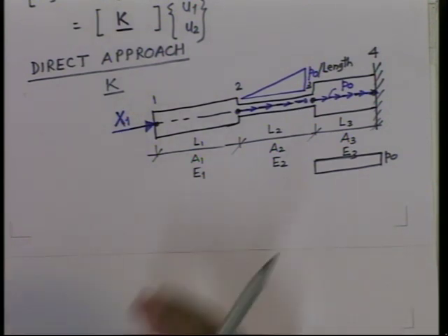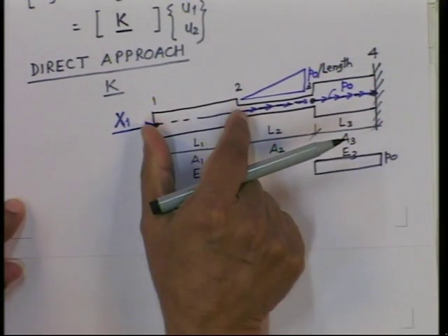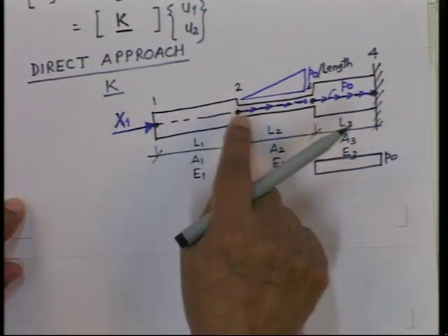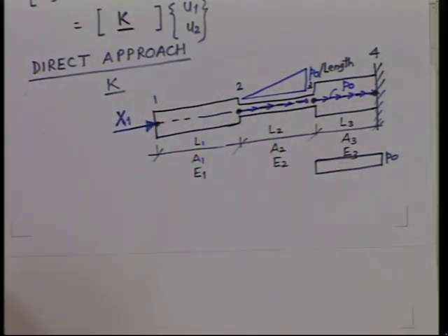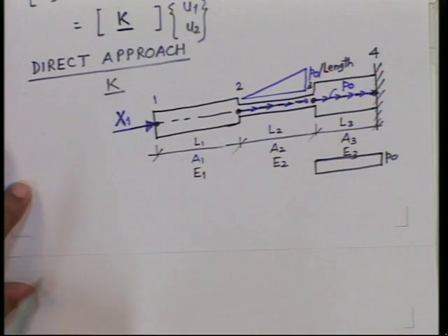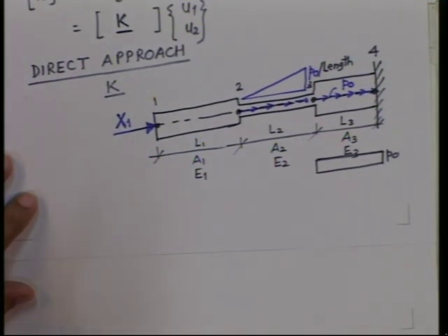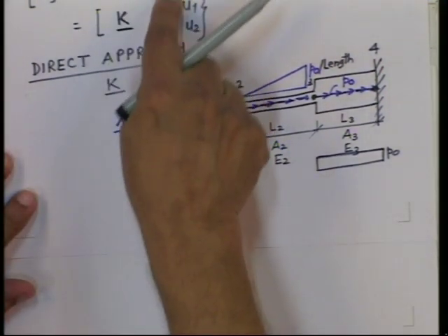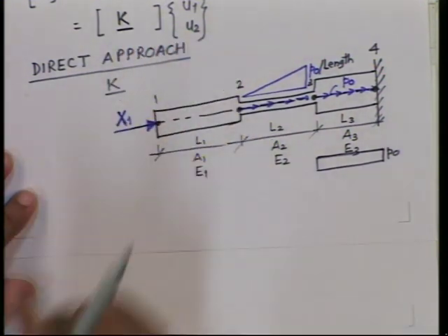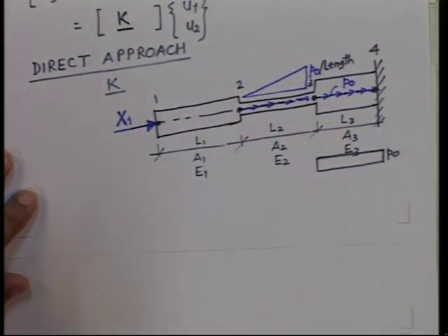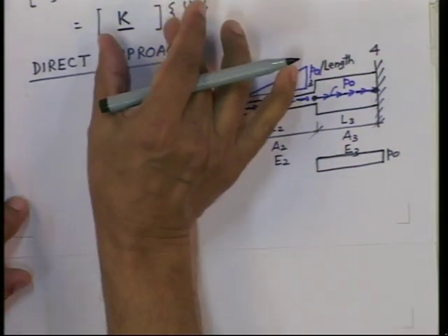We have taken this especially because in each one of these, everything is constant. So, we have taken only one. There is no problem here, because the stiffness that we have got for this member does not vary, it is a constant for the element, and it is exact. For the behavior there is no approximation here.